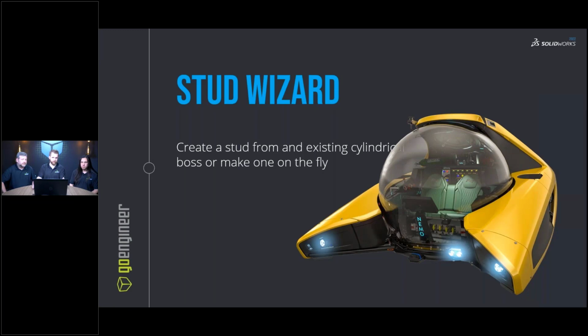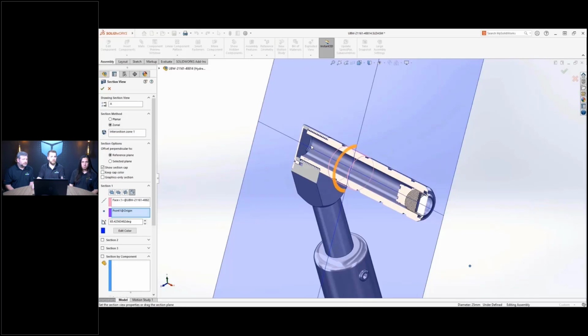In one of the previous versions, SOLIDWORKS included the thread tool, and although it's great, it's always creating modeled threads, which can be pretty difficult for SOLIDWORKS to handle sometimes, and not always necessary. It's great for additive manufacturing or rapid prototyping, but we don't always need it in the model. So the new Stud Wizard has some awesome functionality. It allows us to suppress those expensive modeled threads, and we're able to create cosmetic versions of them. So let's take a look here.